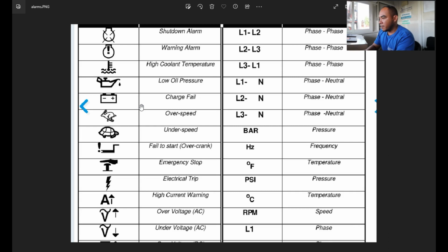Another thing, you also have to check the fuses and the wiring connections, whether they are fitted properly, whether the fuse is still at correct functionality, or there's no busted fuse or loose connections, because these abnormalities of your wiring can affect it. Okay, next is a symbol like this, like the rabbit.